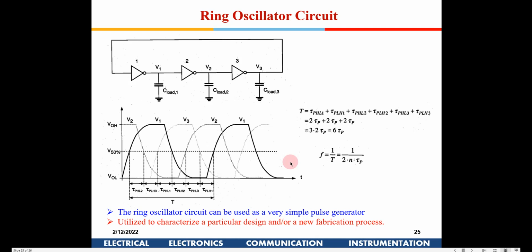If I talk about the inverter, for inverter one, at the output it has the P load one, which is intrinsic. We don't put these loads out here. You make a chain of inverters and you calibrate this, and then you publish this result along with your technology data, so that the user knows this defines the actual performance of these devices in an actual circuit when we are designing.